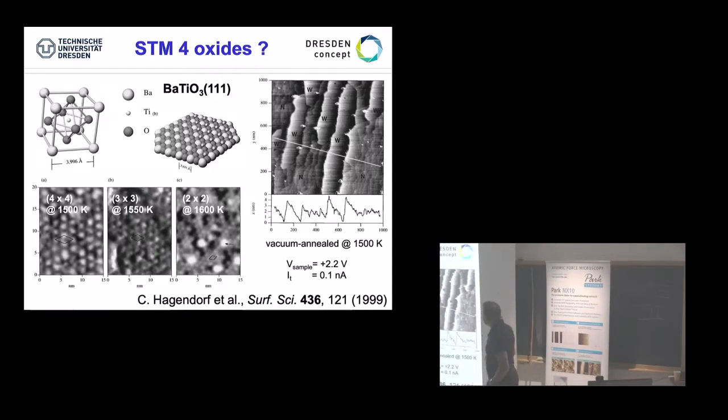Now you can nicely see, this is one of the first scans I did. If you look at these lines, these kind of sausages, I would say, rather striations, these are all parallel to the scan direction. They interpret this as islands or whatever, different regions. The answer is, this is fully insulating. So the interpretation that I did at that time was wrong, simply because you should be really aware of and skeptical. If you have lines like this parallel to your scan direction, you should do something: scan orientation, whatever. And you can see that also in the zigzag. This is charging up with the tip of the sample.